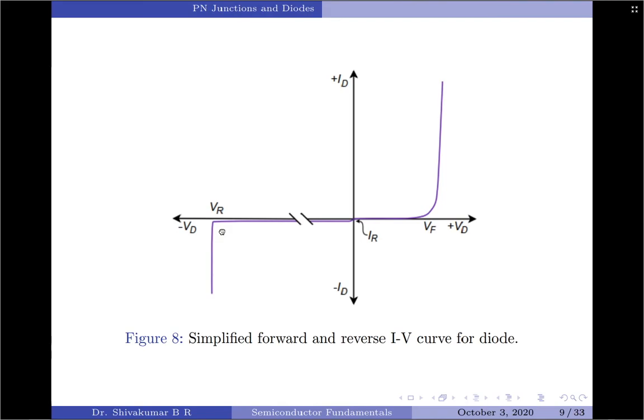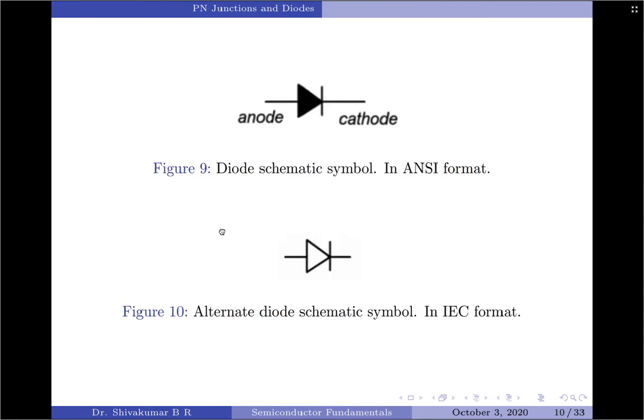In devices using lower levels of doping, avalanche breakdown dominates. In this instance, a high electric field accelerates the free electrons to the point where they can impact surrounding atoms and create new electron-hole pairs, thus creating new free electrons that can repeat the process, resulting in a rapid increase of current. The schematic shown in figure 9 here is for a basic switching or rectifying diode.